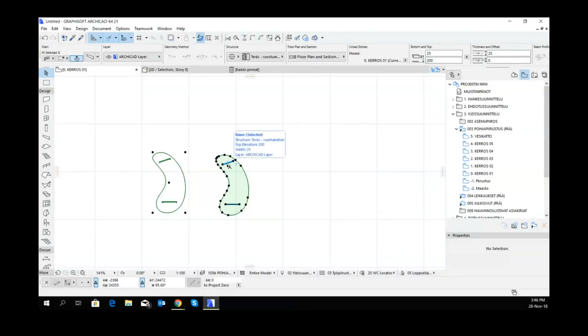Actually, another point before I go too much further is when you model up an object, you can do it anywhere. So you can do it while you're in the project and just out beside the floor plan or whatever. But it's probably a good idea to actually go to a clean file and model the object in that file so that you can then save that file, and if you want to make changes to the object later on, you decide that something's different or you want some other option, you can do it in that file, because if you do it in the main file, you sort of delete it once you create the object, and then if you want to make a change, you have to go back and rework it. So yeah, save a separate file to the side somewhere and keep your object in there.